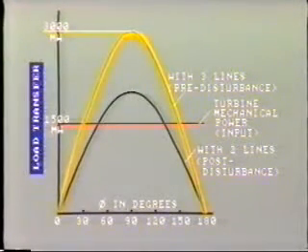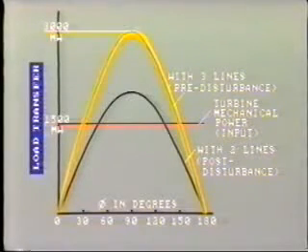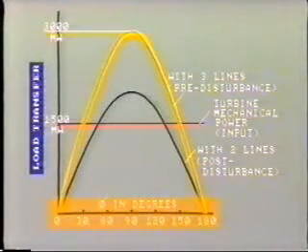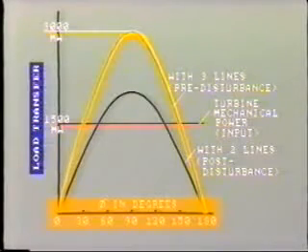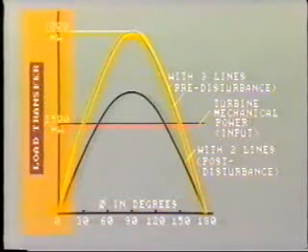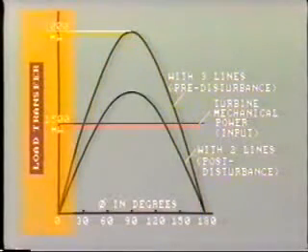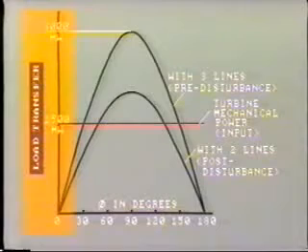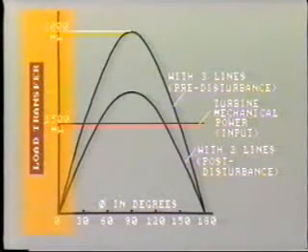This curve does not show speed or frequency, although it is a sine wave. It indicates the phase angle difference between the 2 voltages at each end of the line and the corresponding quantity of power which is being transferred. This vertical axis shows the megawatt output of the generator, and this is, of course, the same as the mechanical input from the turbine, ignoring the exceedingly small losses. Turbine input is considered constant for the very short time periods shown.